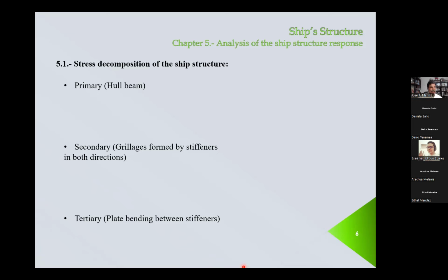Of course, the section is not constant, because at the forward end, the section is like that. In the central part, the section is like this. And the aft, the section is like this, and it's a little bit higher. So immediately you can see that the inertia will change from the forward end to the aft. It's not going to be constant. And that's what I want you to do tomorrow: to take a simplified analysis of this problem. Hull beam.